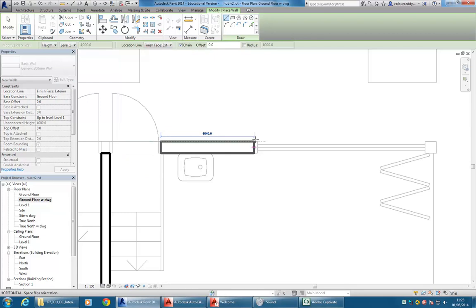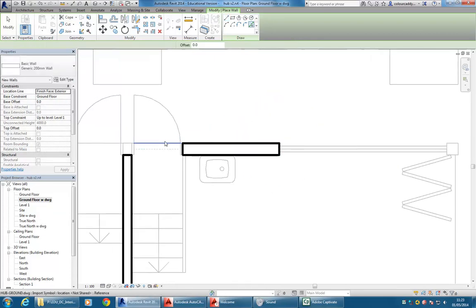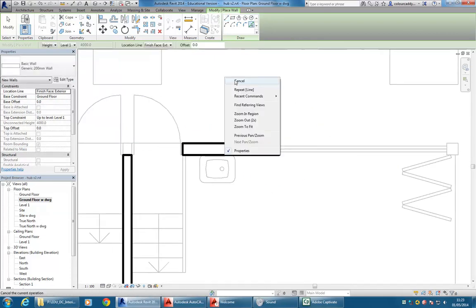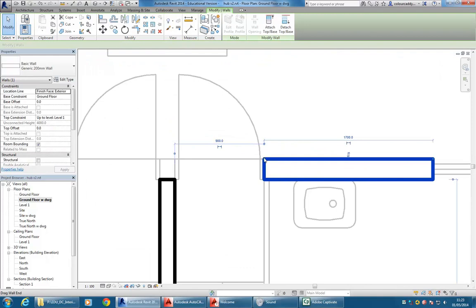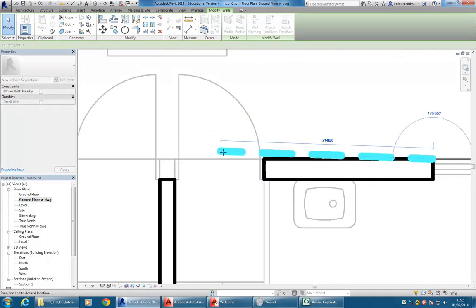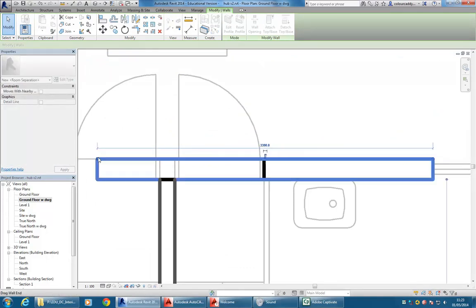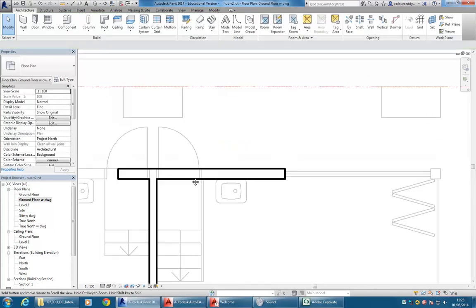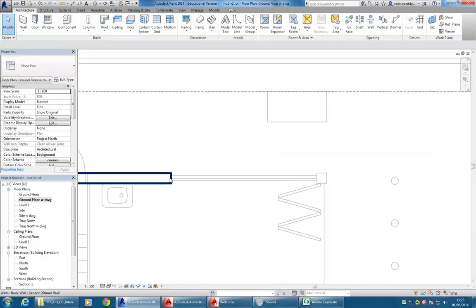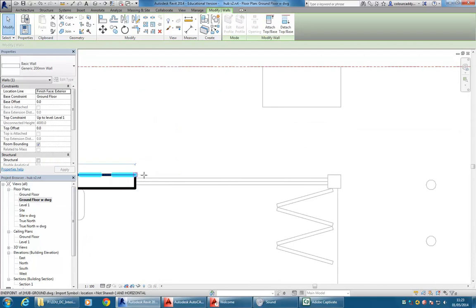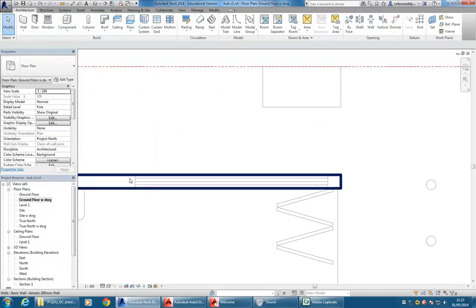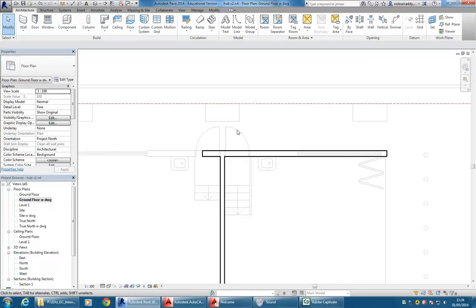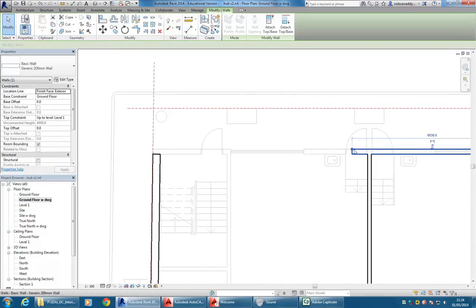Okay, where the wall goes in between the door and the window here, according to this floor plan, again thinking about what's happening in 3D, then you realise that the wall would need to go over the top of that door. So stretch that across. And then also, it really would most likely go over the top of this window as well. So again, you can just stretch that all the way across. And later on, come back and add the window there. And again, stretching it probably just all the way across here.